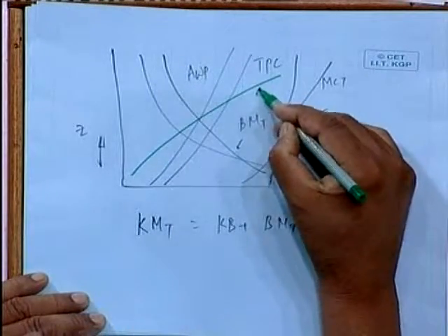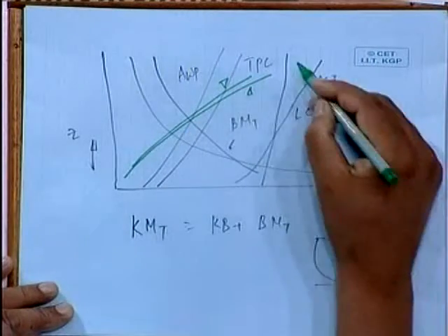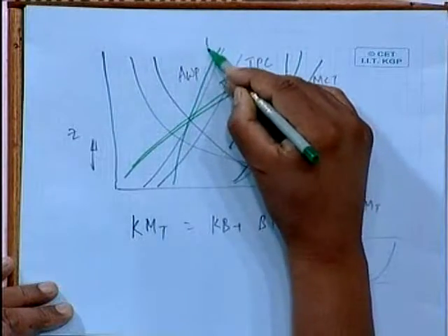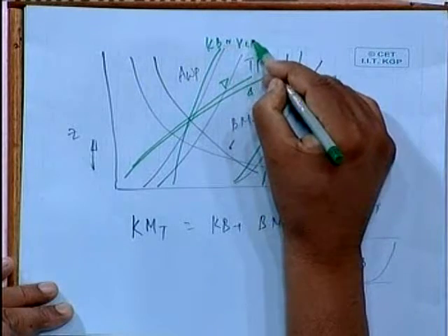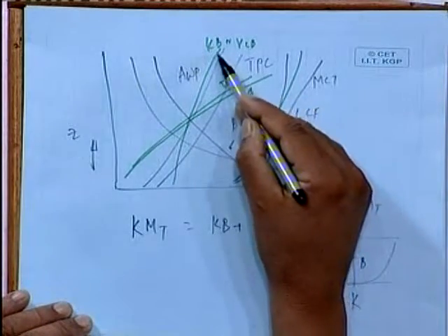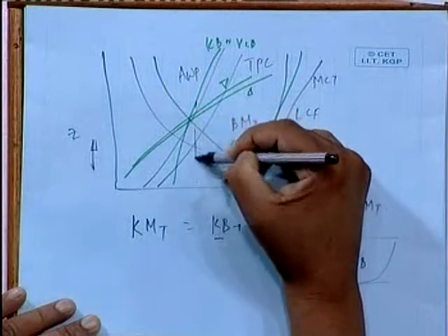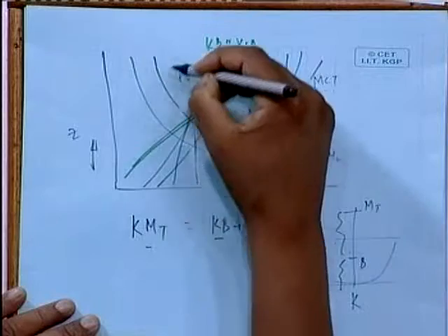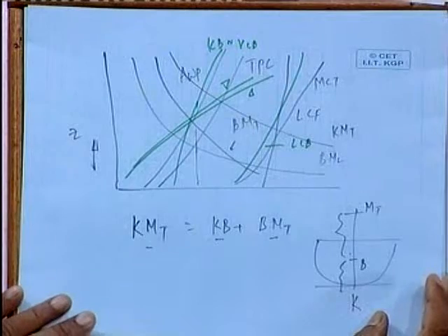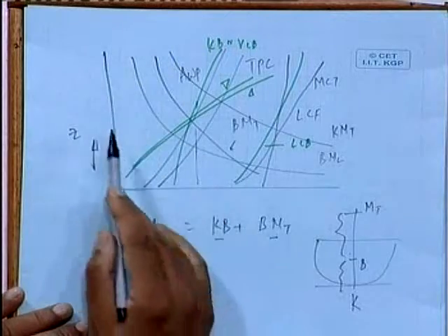We had displacement, we had volume. If you recall, in the previous one we had LCB, and also KB or VCB. We had all this from the previous one. Sometimes if you add KB with BMT, you get KMT. So you can plot KMT also. Say this is KMT, against draft. All these are against draft.